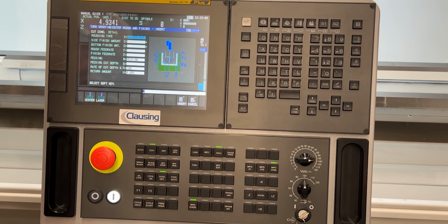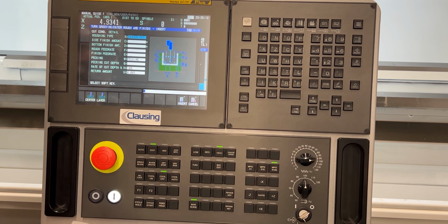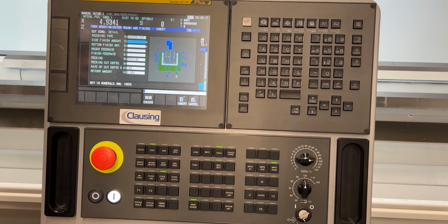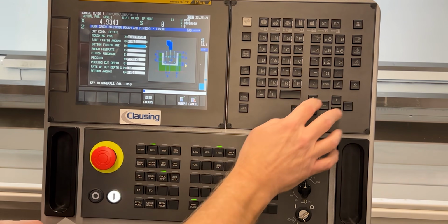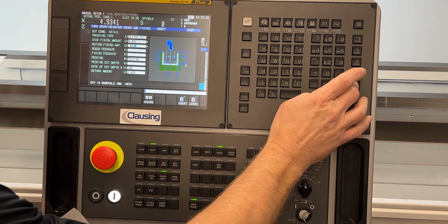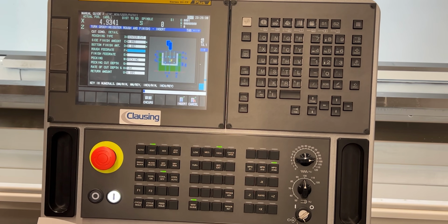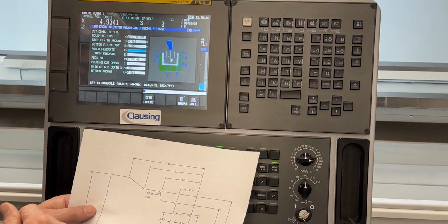That's good for getting coolant down there if it's a deep groove. But in this case, I'm going to use center cut, and I'm going to do how much on the side finish? Let's say 2/1000. Bottom finish, I'm going to leave that at about 2/1000. We don't need very much material in there for finish because you'll have deflection anyway. So when you go to do the finish, you'll have actually more than 2/1000 in there.